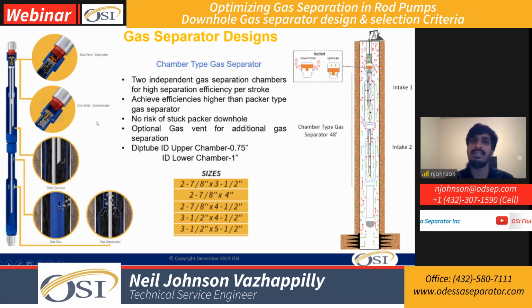Now let's come to our third and final design type. This has not been in the market for a long time, but we've been working on this design for a while, and it's called the chamber type gas separator. The way it works, on the left-hand side, is pretty much like two stacked modified Mother Hubbard style separators, but a critical design parameter is that this middle section has to be sealed so that both of these separators work as individual gas separators.